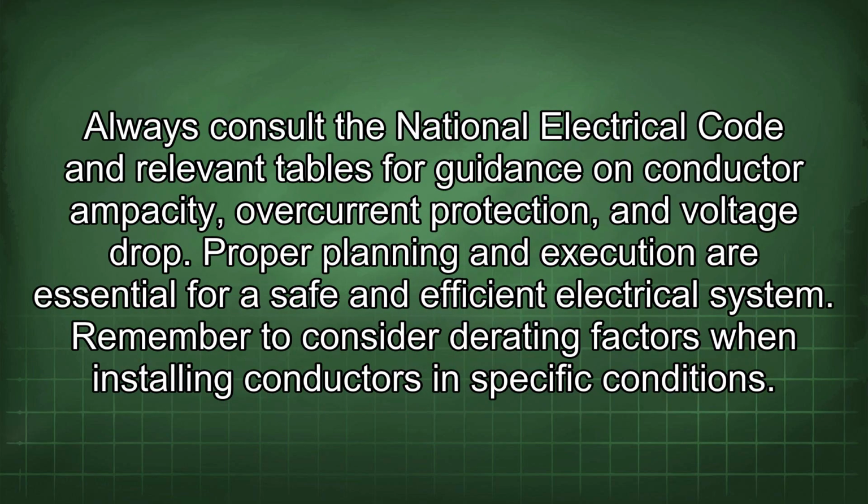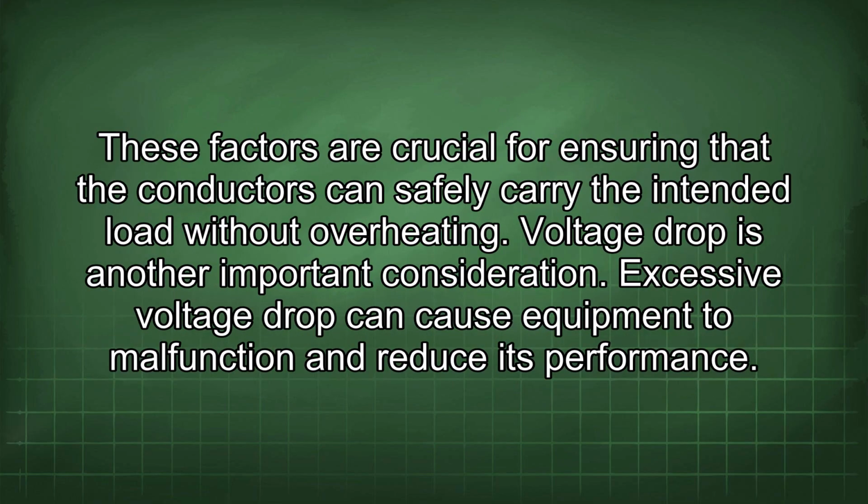Always consult the National Electrical Code and relevant tables for guidance on conductor ampacity, overcurrent protection, and voltage drop. Proper planning and execution are essential for a safe and efficient electrical system. Remember to consider derating factors when installing conductors in specific conditions. These factors are crucial for ensuring that conductors can safely carry the intended load without overheating.